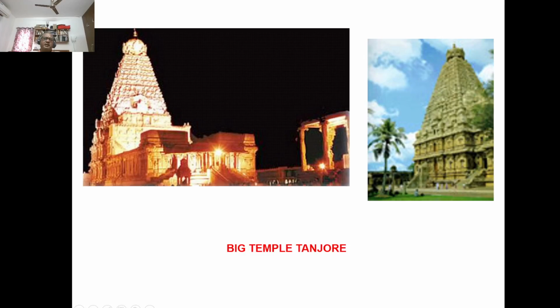The answer is because this is a hollow structure with pyramidal nature, solid at the end and then inside hollow. So the area is suitably done. And then this 80 ton divided by that area is called compressive stress. So there is a pre-compressive stress in every layer, depending upon the area that is there, maybe slowly decreasing also. But if there is a lateral force, in my example 80 ton at 0.2 g is about 16 ton. Suppose you apply it horizontally, first there is friction between two elements, and also there is a pre-compression that exists on this element, which will save it from this kind of lateral forces. That is my guess of how they would have thought of the lateral forces.